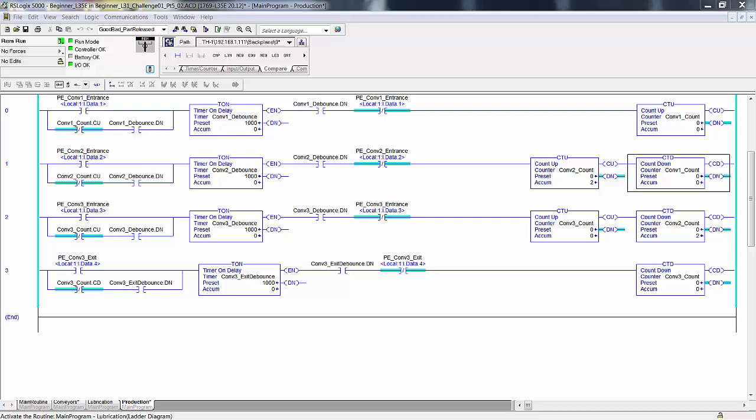Step 5, carton is on conveyor 1 and has cleared 1 PE. Again, decision is to stop or run the conveyor or wait for logical conditions. Remember, what we're working up to is the functional specification for our conveyor motors, and the logic for our conveyor motors, when they run and when they don't run. So in 6, carton arrives at the entrance to the conveyor. Decision is to run the conveyor or wait for logical conditions.